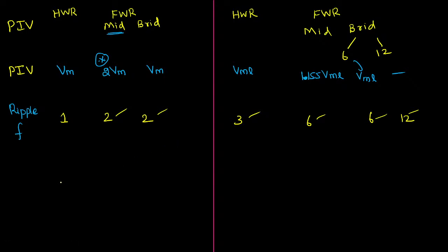Okay, sir. The next question that will be repeatedly asked in the examination is, what is the output RMS voltage? If you keep your attention on the half wave rectifier as usual, the output RMS voltage will become Vm by 2, not Vm by root 2. It is not like the general expression. It will be derived based on the output expression.